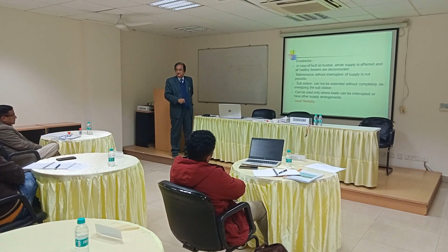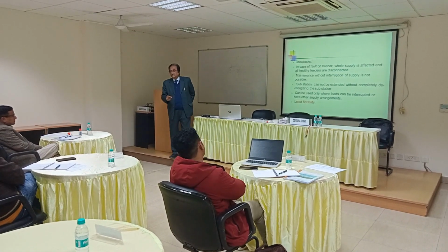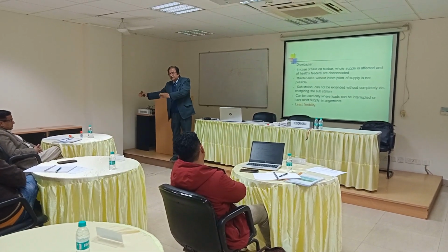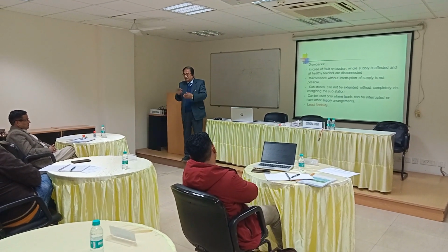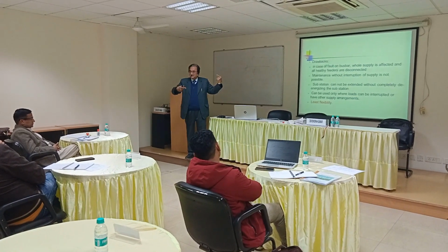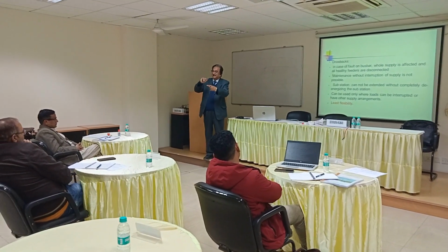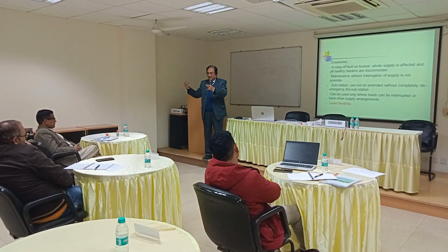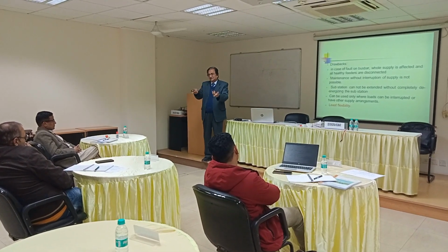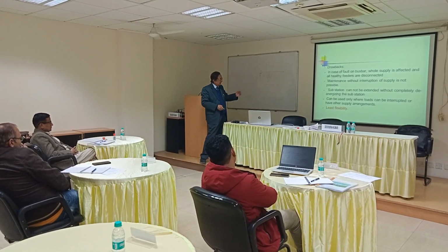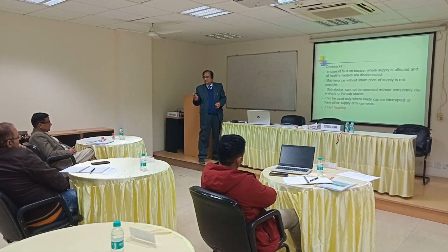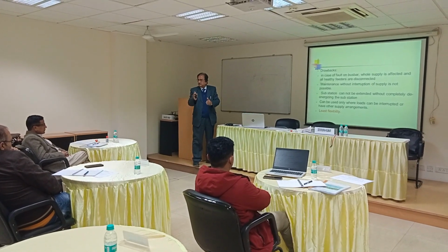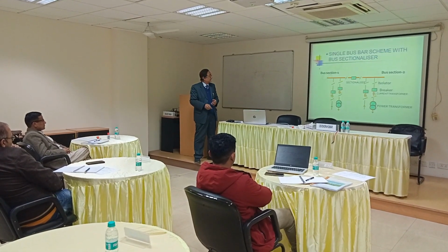Substation cannot be extended. Now, for extension of the substation, what do we do? We erect the equipment in the adjoining bay, but when we have to connect with this bus, the substation will be dark, because we have to take shutdown on the bus bar to connect the extension bus with the existing bus. Substation will be dark. So, it has the least flexibility, because the length of the bus is limited. The number of feeders which can be connected on that bus is also limited.